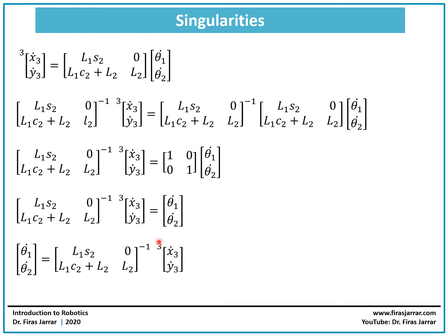Because in this way, if you know the required increments in x and y, so you know delta x and delta y, in order to move along a certain path, you can, using this equation, compute the required delta theta 1 and theta 2 in the same increment in time. And thus we can control the end effector to move along this path, because the changes in theta can be easily sent to the servo motor through the microcontroller.